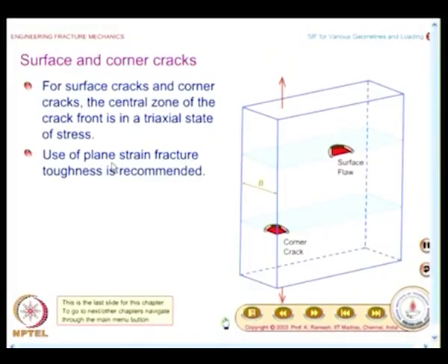And when you have to use plane strain fracture toughness, you have to recognize that surface flaws are always dangerous, because you are always comparing the stress intensity factor of a surface flaw with that of a through the thickness edge crack, but for an edge crack in a reasonably thin plate you may use a plane stress fracture toughness.